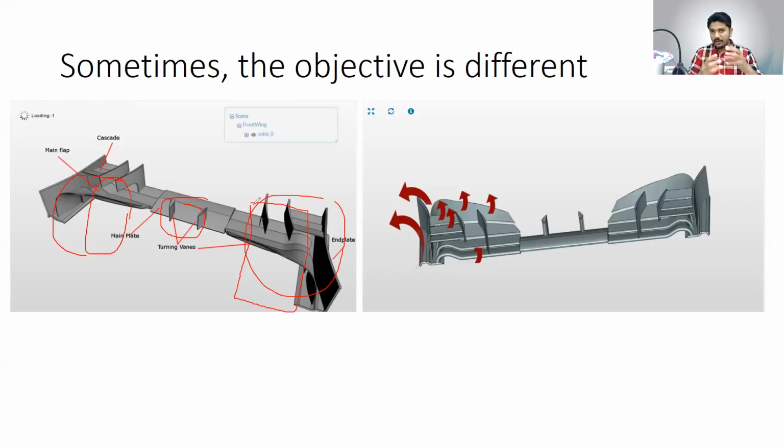And when there is a rotating object and when there is air coming right up front, it's very bad. It's going to cause a lot of drag force. In other words, there's going to be a lot of pressure loss. You're trying to minimize the pressure loss by smoothly navigating the airflow, and end plates are just a technology for that.